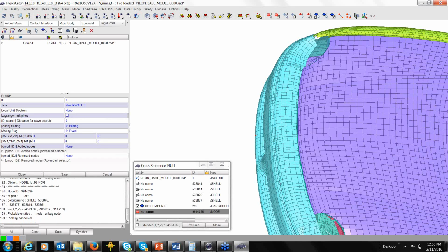If you look at the X, it's 4,000 something. So my wall should be somewhere near 4,000 something. So here, I'm going to create my wall at 4,500, I would say. So I go here and I say, my first point, let's say I'm going to put 4,600. Okay.